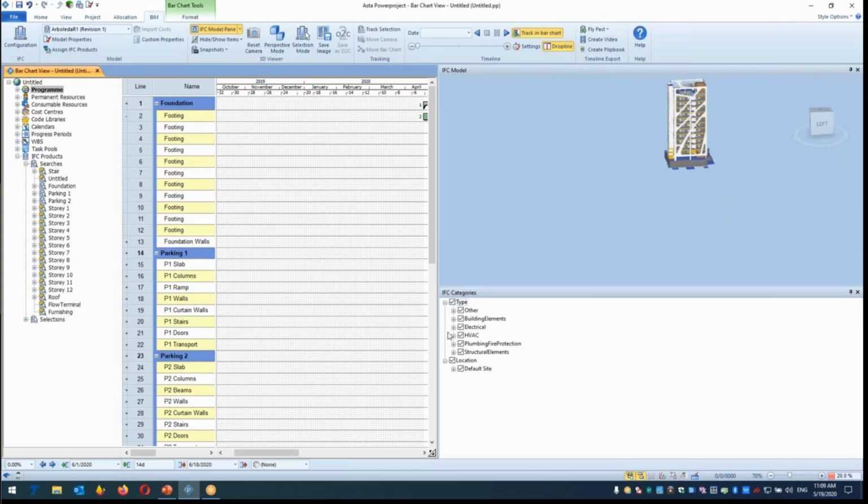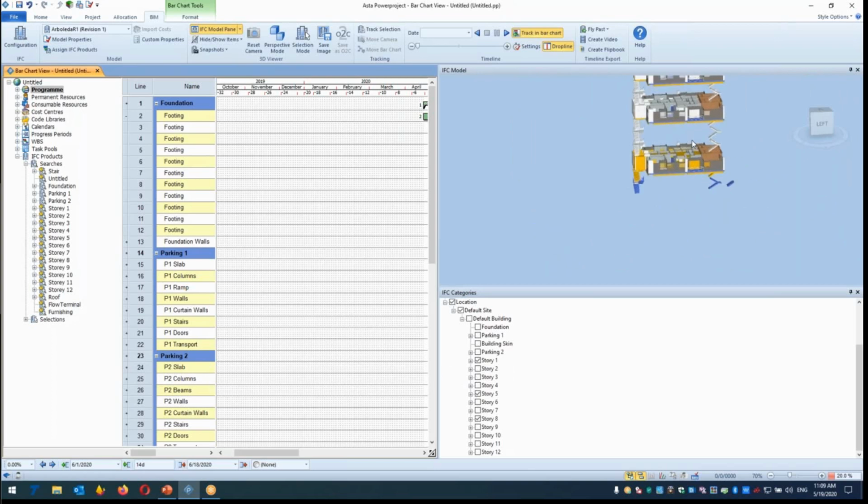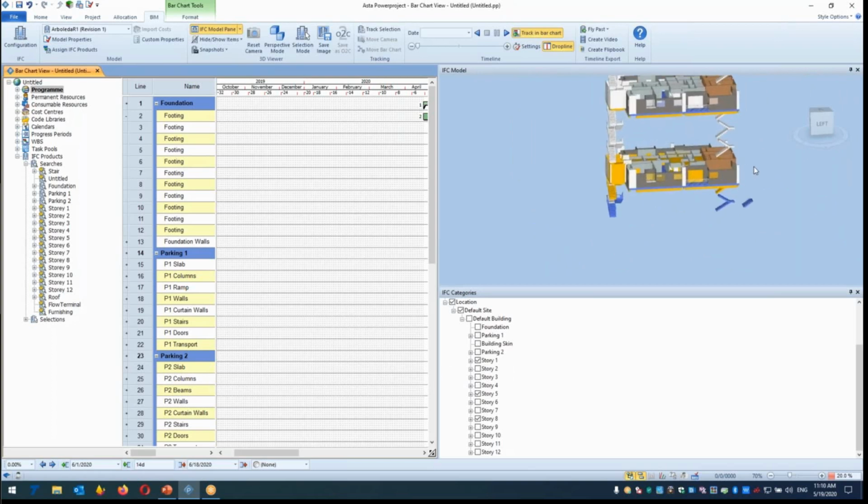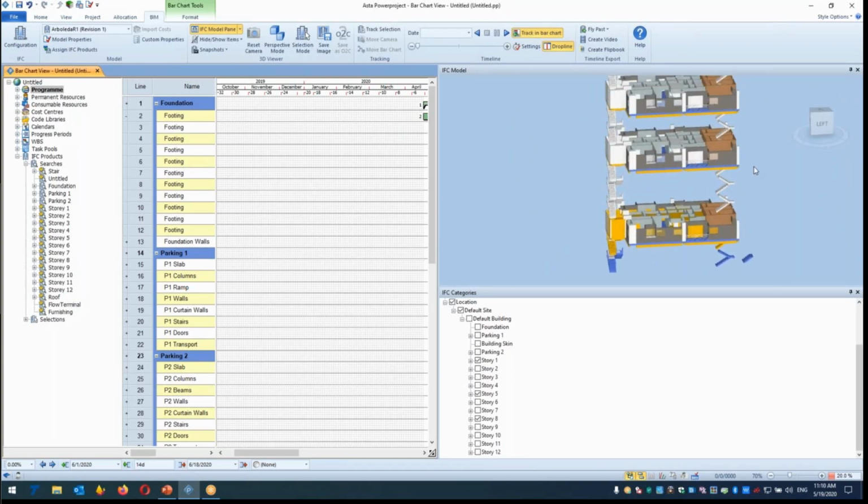From here, you can open locations and link them. I have here just the first floor, fifth floor, and eighth floor. You can just do auto linking by selecting this group of work. Just go to this group of activities so that you can filter and group some activities and link the objects.